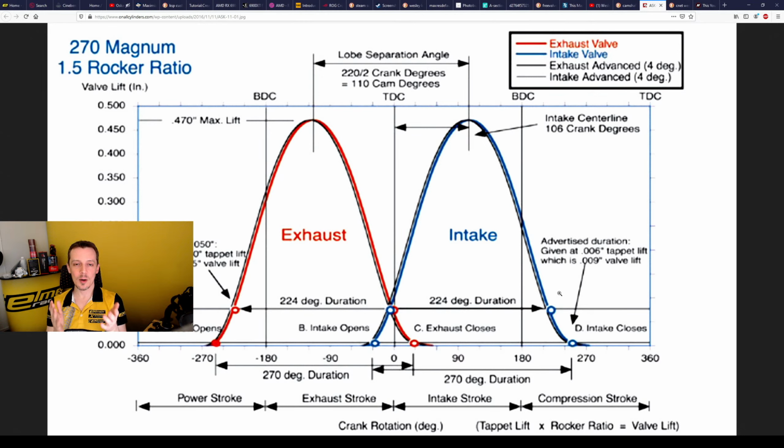So on the RP968, it's stainless valves for drag racing specs, so 3,000 horsepower. I would say maybe at 2,500 RPM and up for drag racing, I might want to recommend Inconel or sodium filled valves. I don't think there are sodium filled valves available that big though, so I don't think that's actually an option. So might need to do Inconel valves in that case.